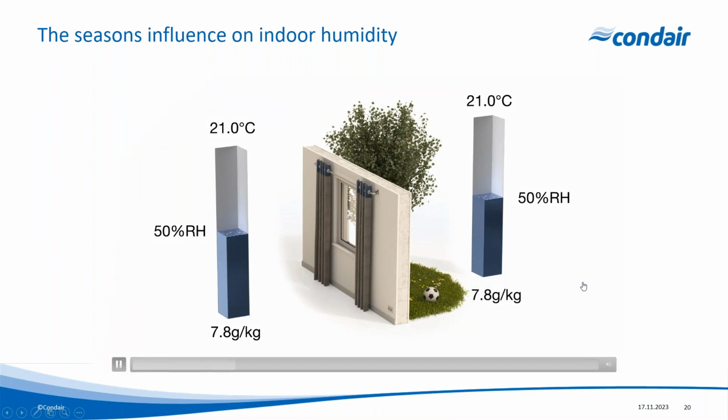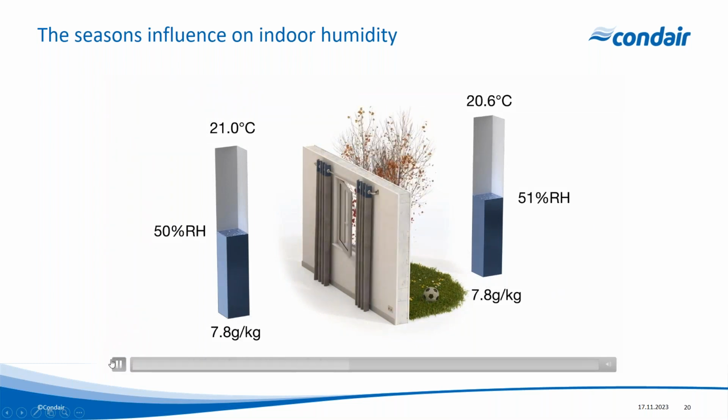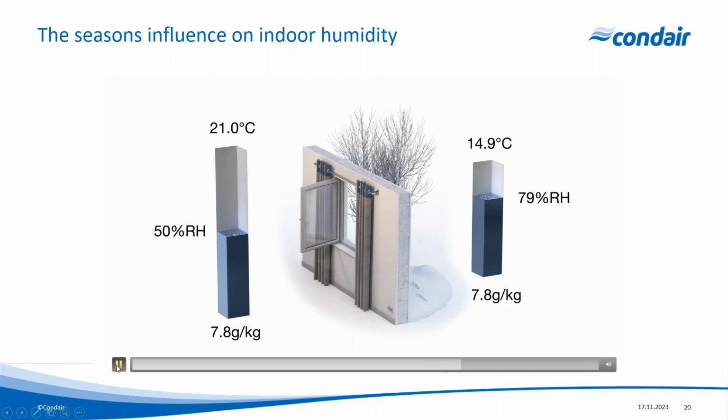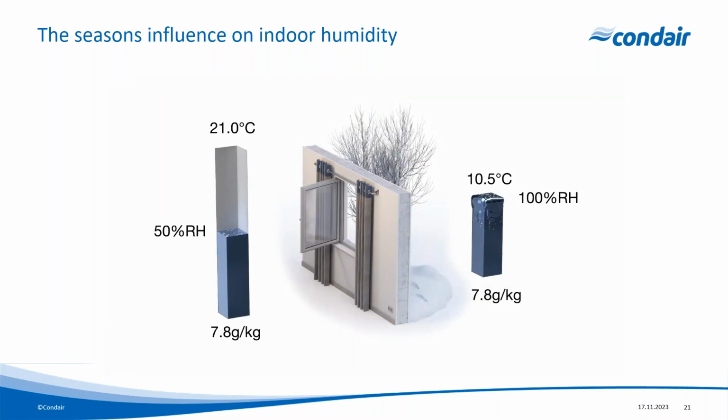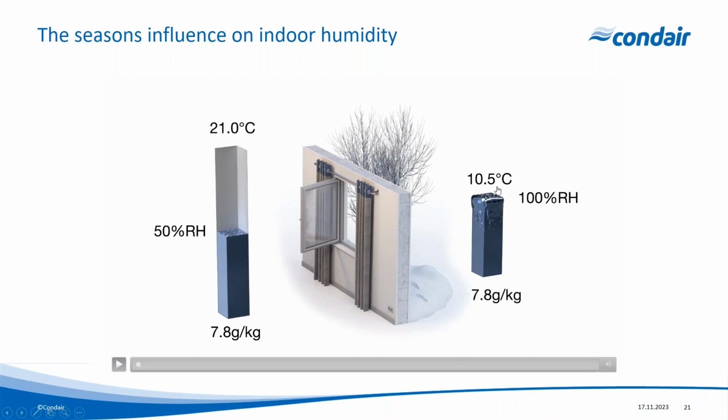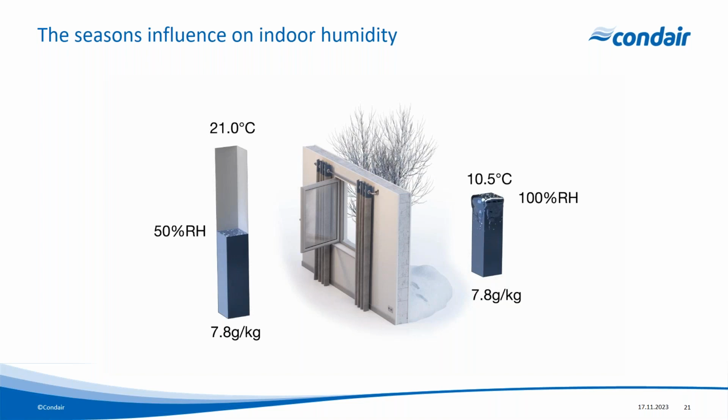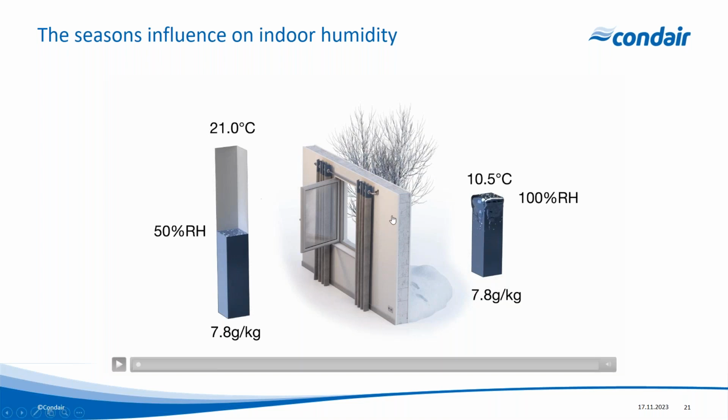But let's say that outdoor air then gets colder. You can see that air, when it gets to 10 degrees C, is completely saturated. That is kind of okay at this point, because when that air at 10 degrees C saturated comes into the indoor space, it's still got the same absolute moisture content as is required to satisfy our 50% RH at a higher temperature.